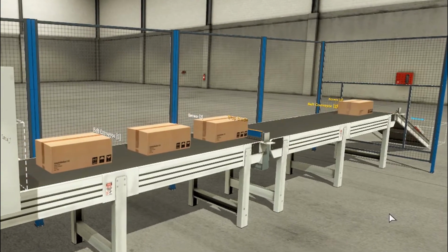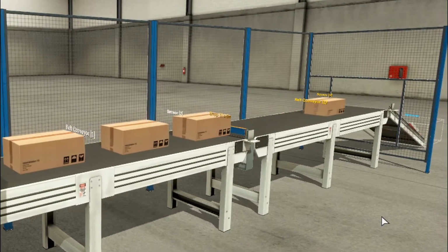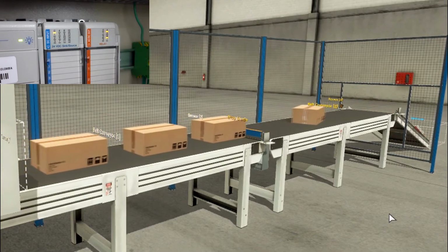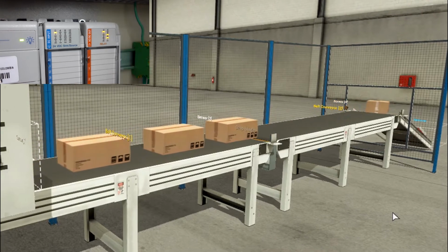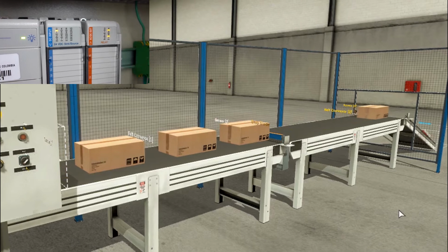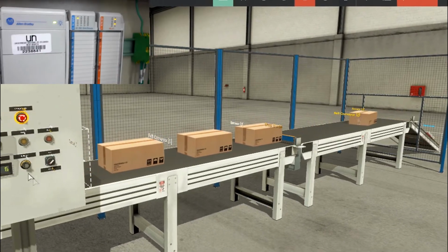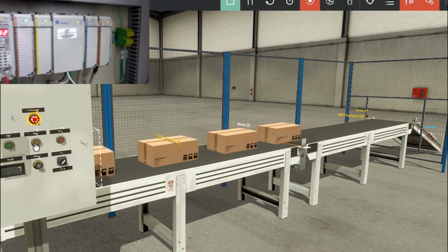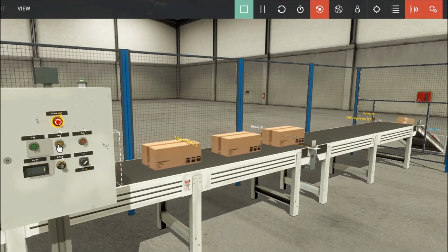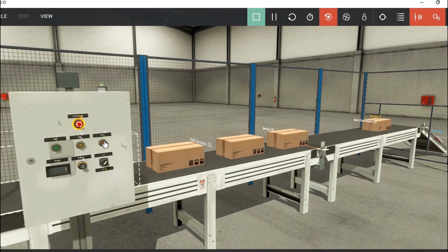At the end of the exit conveyor belt, we can find a second sensor that, when detecting the box, will open as a switch to release the blade and activate the buffer conveyor again, allowing the next box to pass and then repeating the process indefinitely. In addition, we add a counter on this second sensor to display how many boxes have left the station in the panel of Factory I/O, and a reset button to restart the counter back to 0.